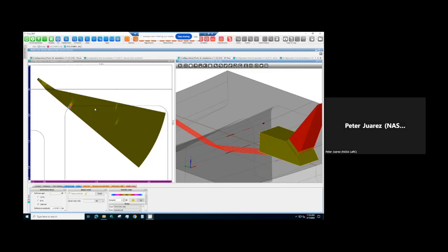And the reason that this happens is because there's what's called an acoustic impedance mismatch between the probe, the adhesive, and the rest of the structure. What acoustic impedance mismatch means is basically how much energy gets transmitted and how much energy gets reflected when it interacts with the interface between these two materials. And so there's such a difference in acoustic impedances. A lot of the energy gets reflected back at the probe before it can get in. And then when it's coming back out of the structure because it reflected off something, even less is getting past the adhesive and then getting back to the probe.